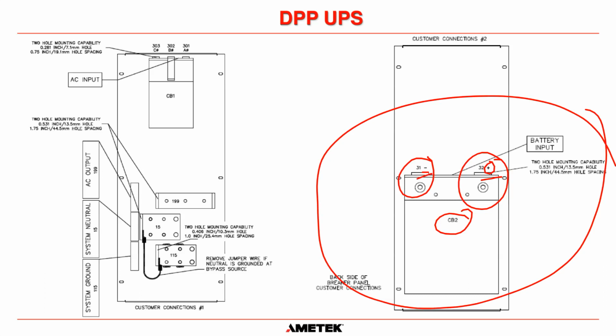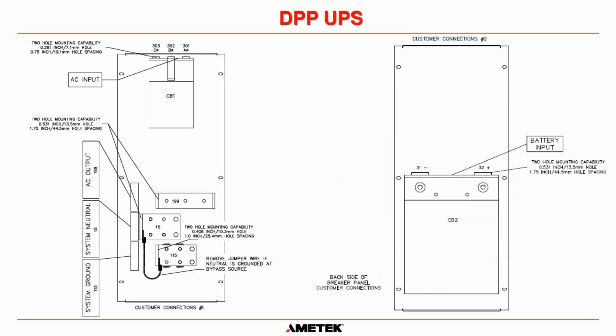Okay. And before you ever close this breaker, after you have initially connected the cables, you always want to check. You want to turn on the UPS, turn on the charger, and you want to make sure that you have positive. So this is the output of the charger on the bottom side of the breaker. You're going to have, for a 60 cell system, 135 volts there.